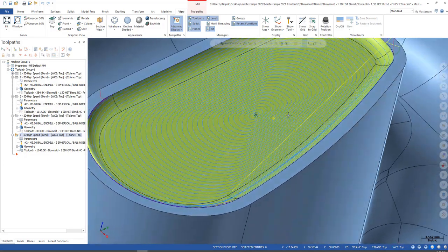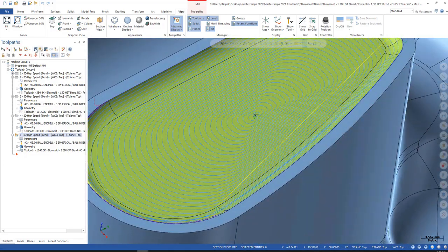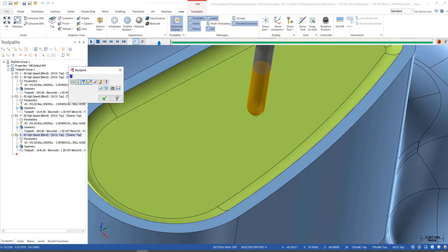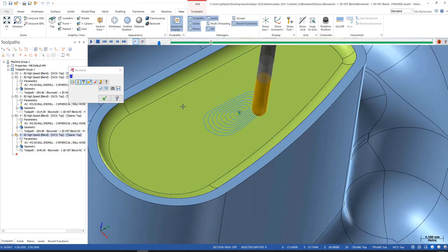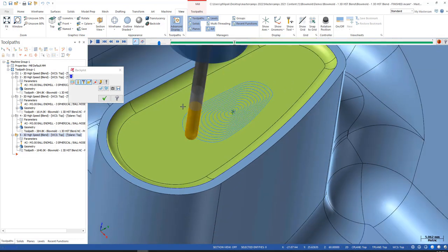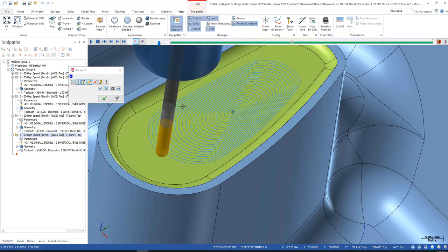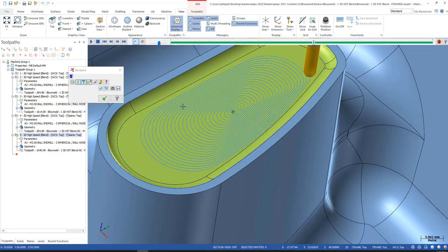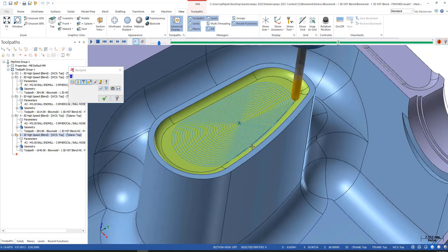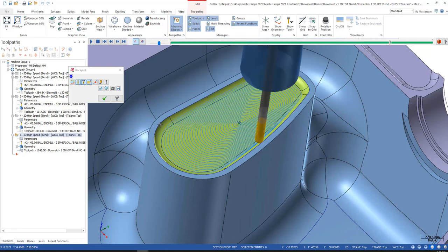And there's my cut. Just by turning it to spiral, now I'm going to have one lead in on this part. It's just going to spiral out with no transitional move. That should be that much smoother of a finish, maybe less handwork to be doing on them parts. So just keep in mind the spiral option and try her out.